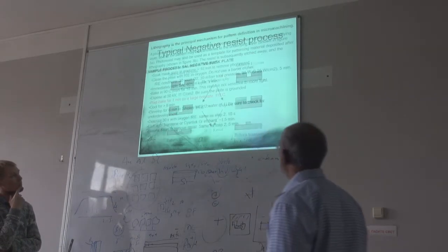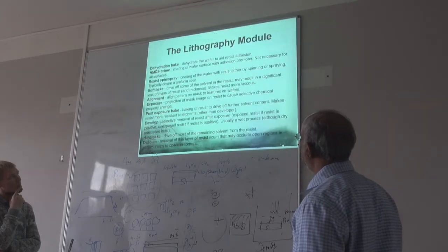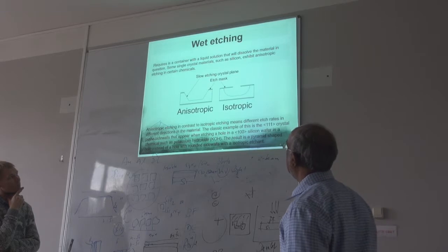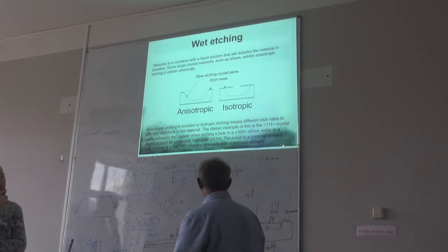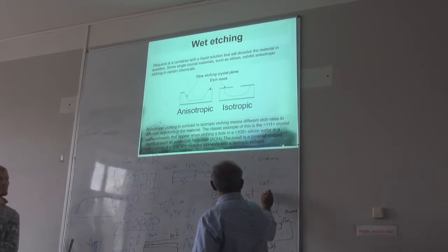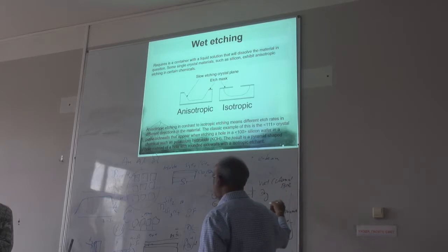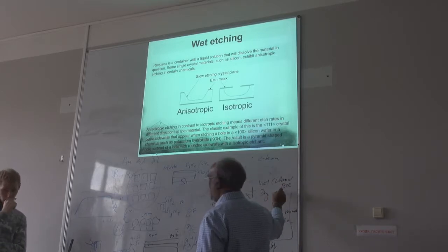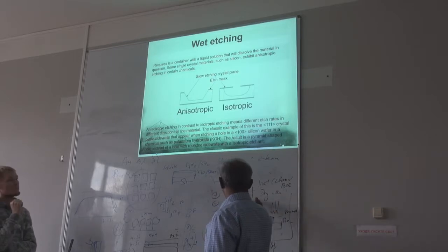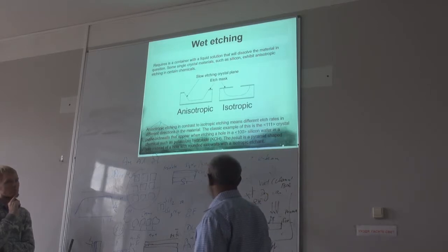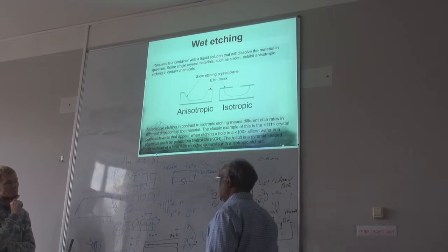Okay, so now there is also the etching we talked about. Like I said, there are two kinds of etching, right? One is wet etching, the other is dry etching. Wet etching is all chemicals, so we use buffer oxide etchant. For dry etching, mostly we use what's called reactive ion etching, or we can even use a xenon kind of gas, and we can do deep reactive ion etching.